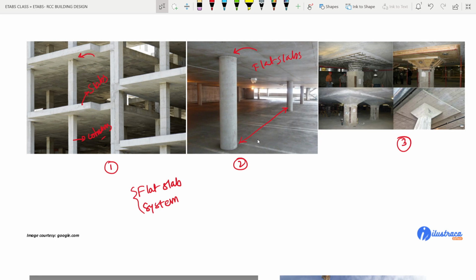Okay, we will understand what this particular span is. Generally, we consider 4 to 5 meters or maybe 3 to 4 meters. But in that case, you may have very high spans between two columns. The thing is, this system is not recommended because we do not have a secondary medium to transfer the load except this column and this column, right? So if any of the parts, suppose this particular part, fails, there will be nothing else to take the load of this flat slab, right?